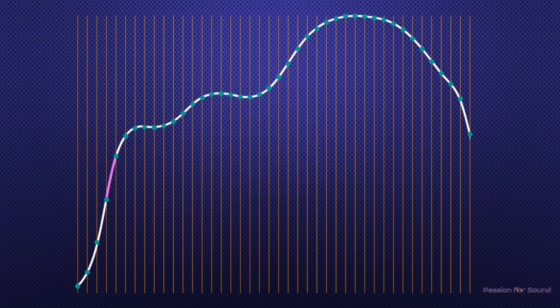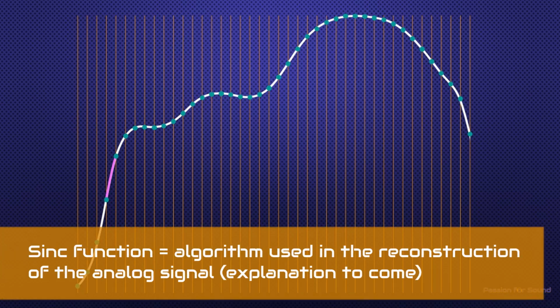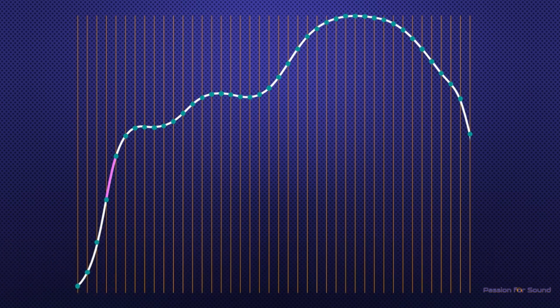The difficulty we have here is that interpolation filters are not very good at reconstructing the bits in between. And we know from theory that we can perfectly reconstruct the original bandwidth limited signal if we use a sinc function. Now, a sinc function requires an infinite amount of processing, so we can't use sinc functions in reality. Now, the reason why it's important to reconstruct the waveform from one point to the next point is about transients.